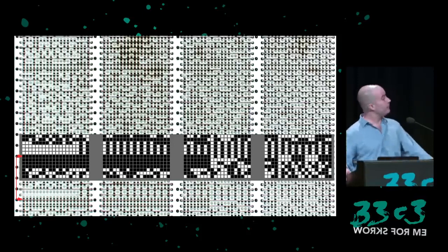In this image, I've overlaid the extracted bottom 13 rows of bits over the photograph. You can see some visual patterns inside this also, and these visual patterns are a good indicator that this ROM is probably not scrambled.